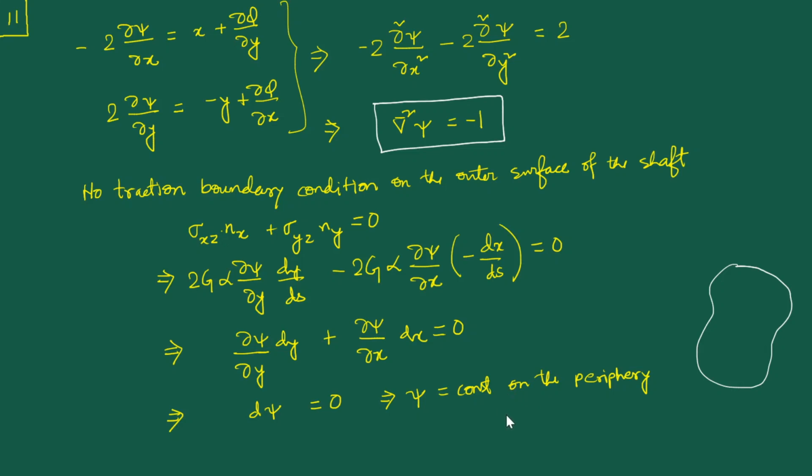Another very important thing to note is that because this is a constant and because the only connection that this psi has with the stresses is through the derivatives, it really doesn't matter if we add or subtract certain constants from this. Okay, so we'll exploit those things later on while addressing the various examples.